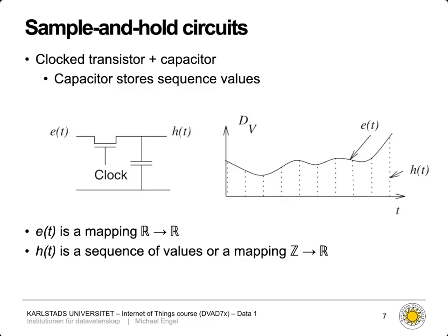But nevertheless, this is the first step we have to do. So now, using the sample and hold circuit with an appropriate clock, that should obviously be as fast as our data acquisition system is able to work, now we can have discretized analog values at certain amounts of time.